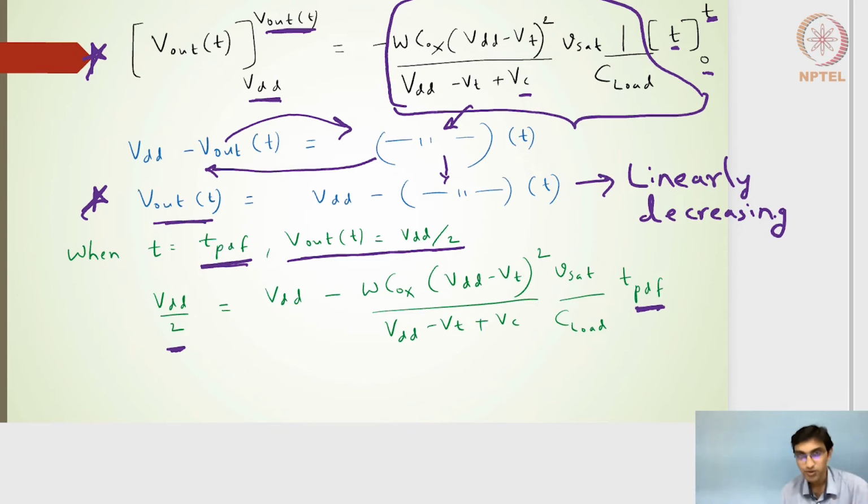We will need to calculate the propagation delay falling, because the propagation delay falling is the point where the output voltage decreases to 0.5, and the VDS value, the saturation value in the short channel current model, is well within that 0.5 volts. So the NMOS transistor is still in the saturation region, it changes from saturation to the linear region only at 0.411 volts, right? So no need to get the exponential profile in the short channel current model to calculate the propagation delay falling. All right, hope this is clear.